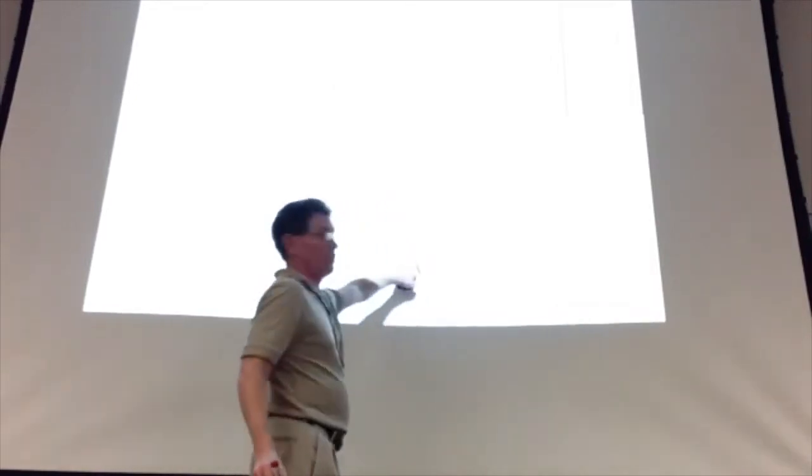I have an extra t squared here; this was t, not t squared. Plus 5 times 4, and that last one is just t. These are all from 0 to t, evaluated between 0 and t, plus the 1. Now we put in the limits of integration. So we're going to have 5t cubed plus 5t squared plus 20t plus 1. And that gives us our final inductor current.